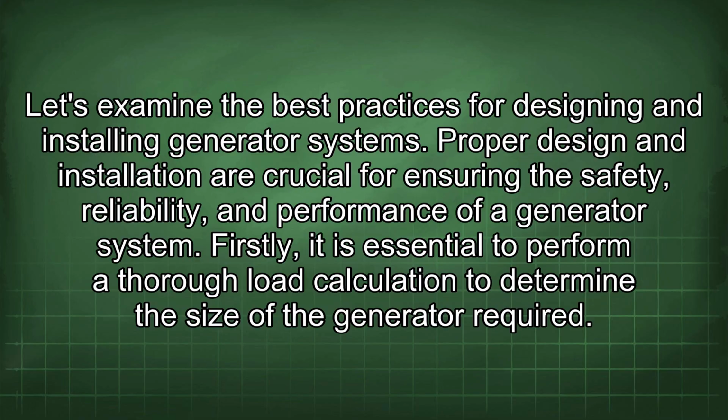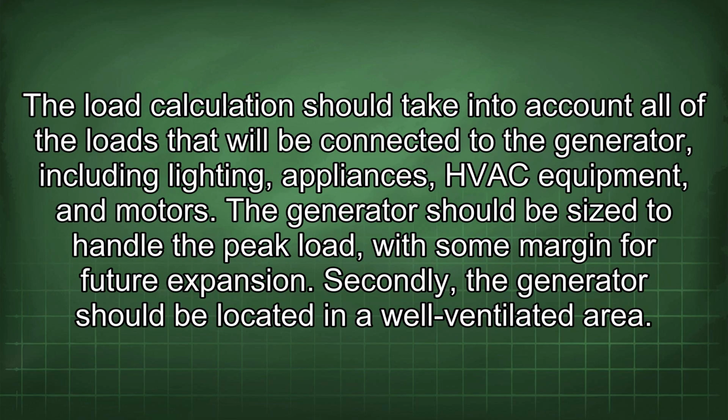Proper design and installation are crucial for ensuring the safety, reliability, and performance of a generator system. Firstly, it is essential to perform a thorough load calculation to determine the size of the generator required. The load calculation should take into account all of the loads that will be connected to the generator, including lighting, appliances, HVAC equipment, and motors. The generator should be sized to handle the peak load with some margin for future expansion.